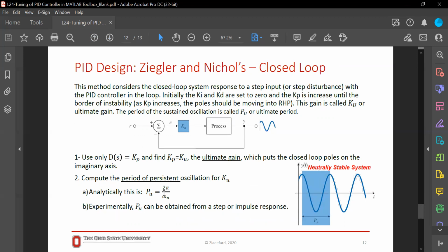Now, the Ziegler-Nichols method is very good for coming up with values that will help the system reject disturbance itself. So when we are designing a controller, we usually check the tracking, right? But this method will guarantee that it will also reject disturbances as well. Okay, so you might find the Ki, Kp from this method not equal to what you find from other methods. The reason is that, again, as long as it meets your requirement, it doesn't matter. It's a good controller, right?